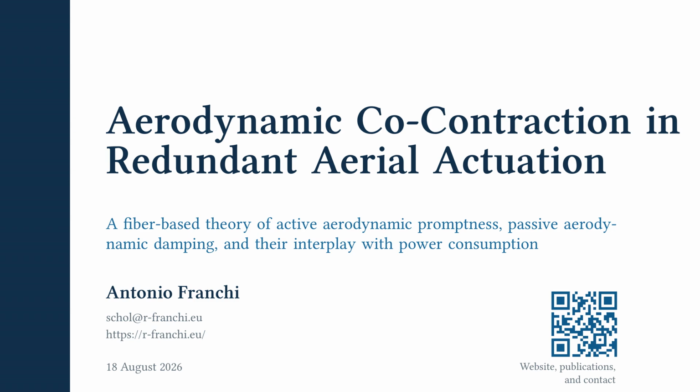Welcome! This presentation brings together two complementary results on aerodynamic co-contraction in redundant aerial actuation. The common geometric object is a task fiber, a family of internal actuation states that all realize the same task. Moving within that family can change active aerodynamic promptness, passive aerodynamic damping, and power consumption.